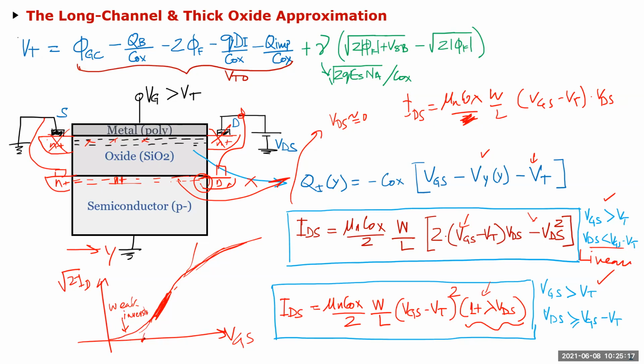So the current is really not zero when VGS is below VT0. So this is an additional effect. And then once the voltage gets higher, the electric field gets higher, then you start deviating as well, and that's what we're going to talk about.